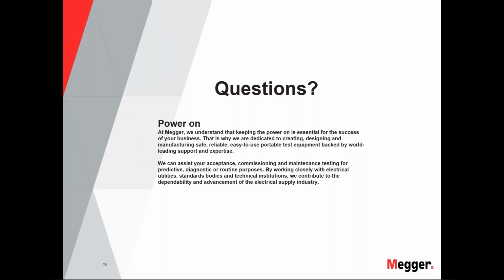Okay. First thing on the rotor ground fault, we have different methods to protect the rotor, like impedance schemes, like the controlled impedance scheme and the injection principle. In case of the injection principle, it's pretty straightforward. With the generator offline, you can make the ground anywhere, then it will work. Then the first and second ground fault happens in the real controlled impedance mode.